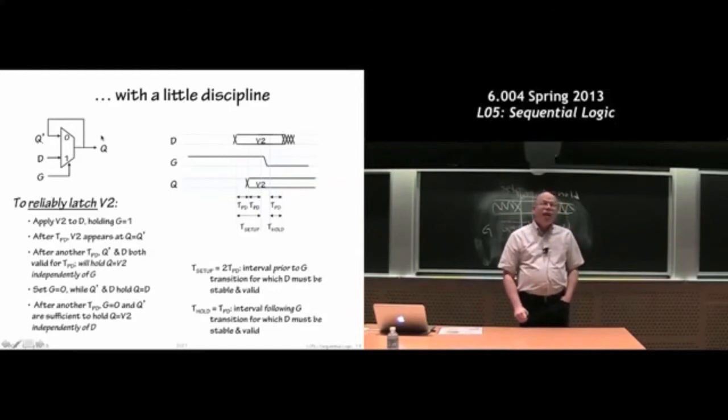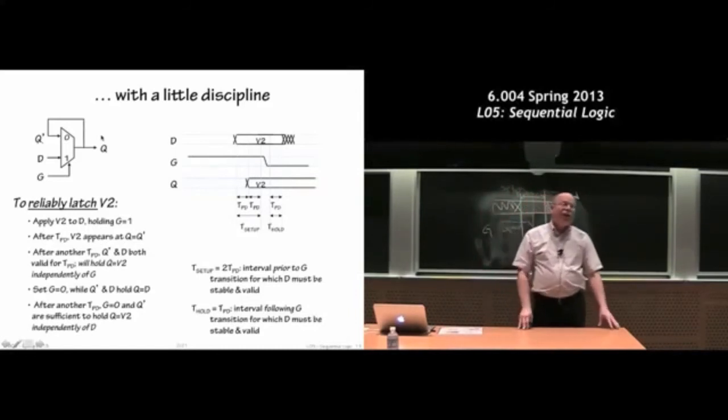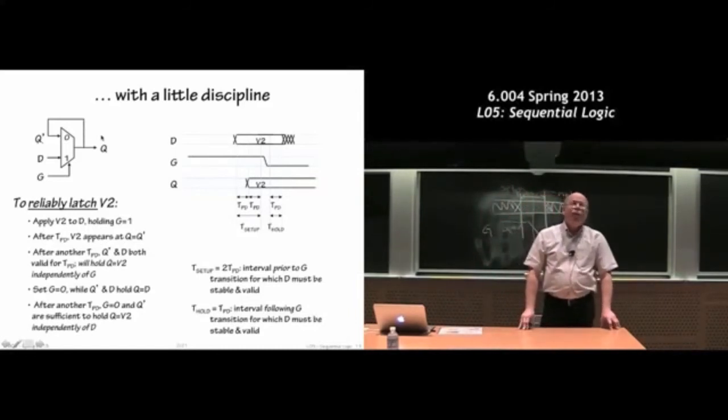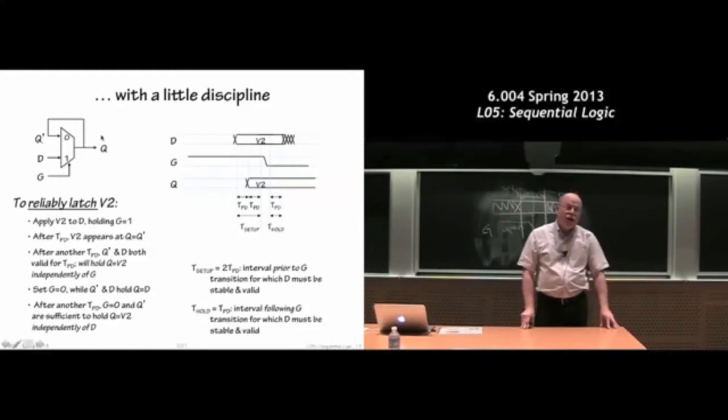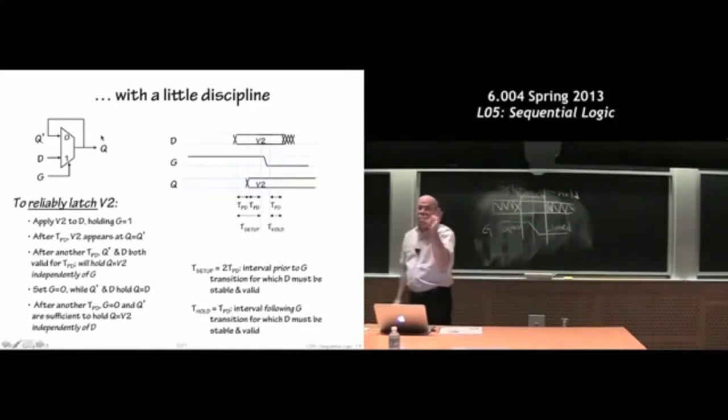And as we'll see when we start using latches in larger circuits, that will be very important for us when we're doing the engineering of those circuits. We'll have to make sure that the inputs to these latches aren't changing too close to when we're going into memory mode, in order for the memory to be reliably set without any possibility of corrupting the value we're trying to remember.